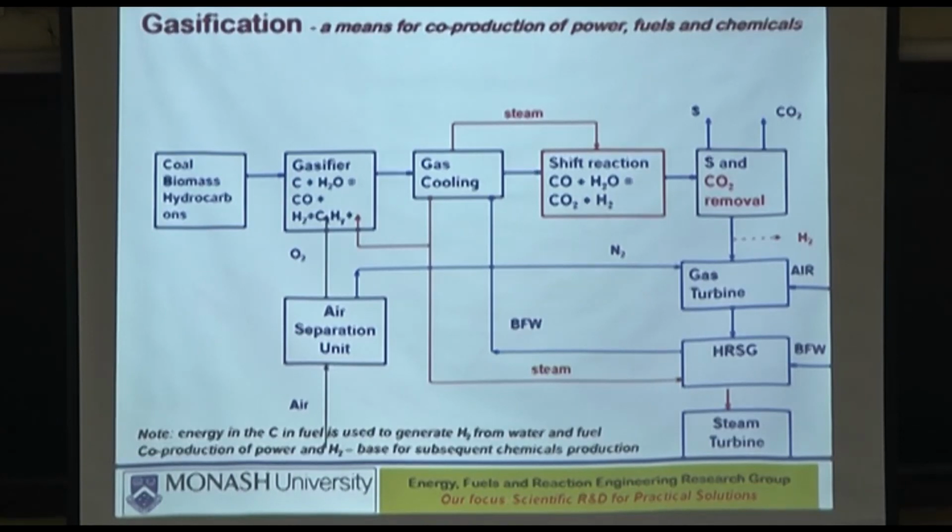Okay, so the gasifier, in one of the few slides later, I will show. In the gasifier, what happens? Some amount of drying will happen, depending on what the moisture content is going with the coal, 2, 3, 4%, whatever. Then pyrolysis. Pyrolysis will produce methane, right? And at those sort of temperatures, you won't get much above methane.